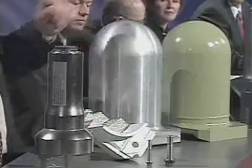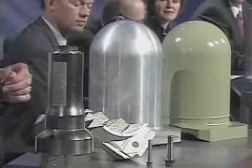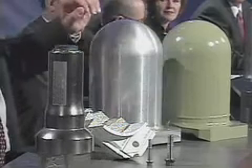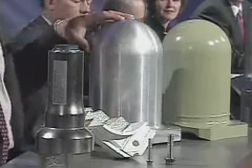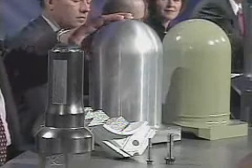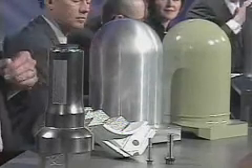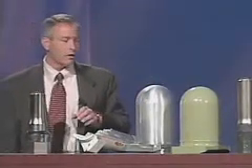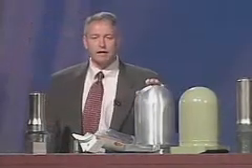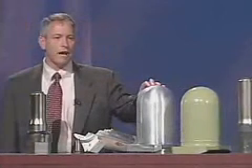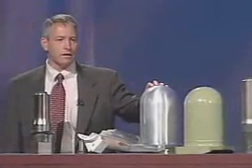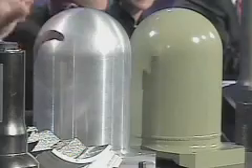It's a cork material. Relative to the specific changes we've made, they're both aluminum alloys, but this bolt catcher is aluminum alloy with a little bit more strength. It's about 12% stronger than the old bolt catcher from a material standpoint alone. We've also increased the thickness of the bolt catcher from 1/8 of an inch to 1/4 of an inch. So we've doubled the thickness of the bolt catcher itself.